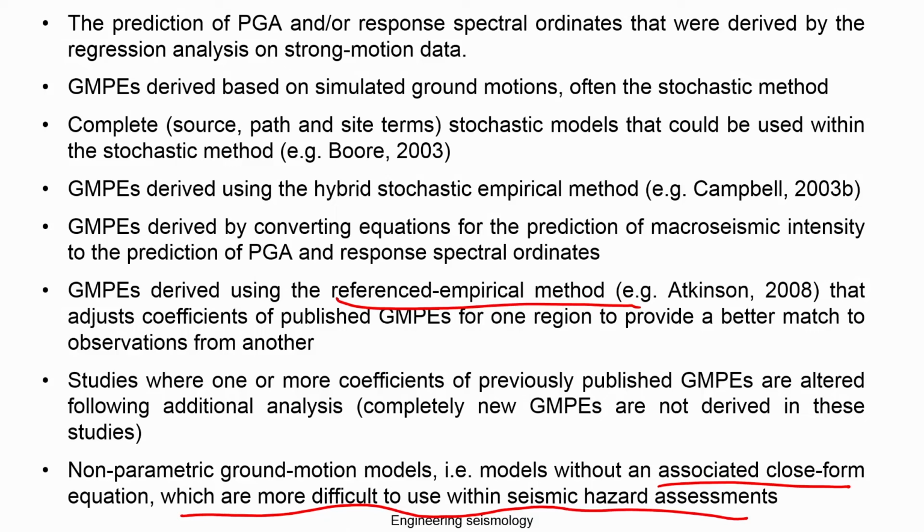Apart from that, as I told you, when you look at this report, a large number of ground motion prediction equations are available, like 302 plus equations. Which equation is applicable to which region, and how reliable is it? That process is called selection of ground motion prediction equation. I also do research on that, and we have published a couple of papers on selecting the most suitable ground motion prediction equation for a region.